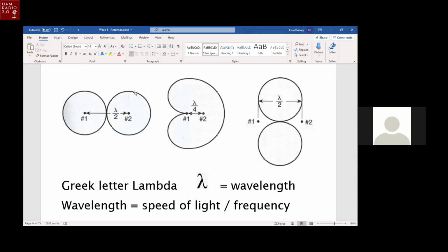And if you get an antenna book, ARRL antenna book, or I've even seen it in the radio amateur handbook from ARRL, or just search online for how to feed vertical antenna array. You'll see arrangements of relays and coils of coax that form phasing lines. They're called phasing lines, is what I've seen them called, and get some ideas how to do that.